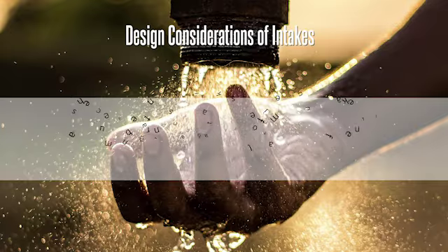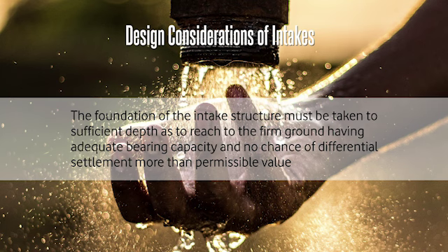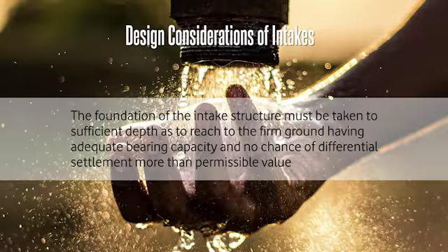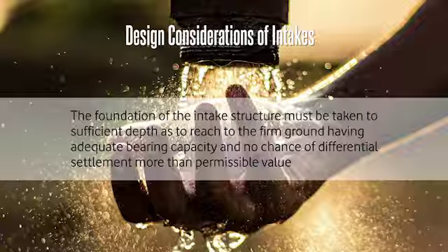The foundation of the intake structure must be taken to sufficient depth as to reach firm ground, having adequate bearing capacity and no chance of differential settlement more than the permissible value.